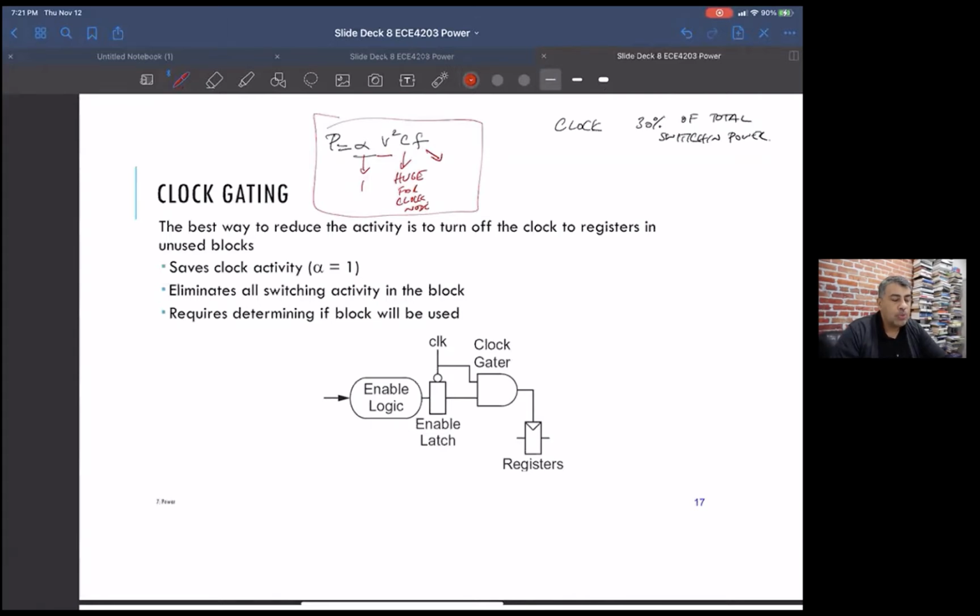And so what you want to do is this: because of the way you set up your processor circuits, some circuits aren't really doing anything. Unless you do something about it, they're still constantly getting clocked, right? We talked about a flip-flop, or let's just draw a latch. Something like this. So even in the simplest case, when nothing's happening, you're still clocking the gates on your clock, even if the inputs aren't changing.